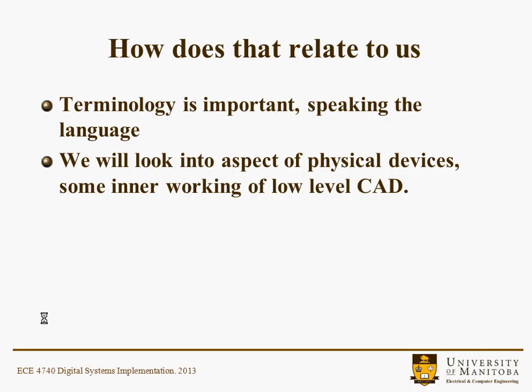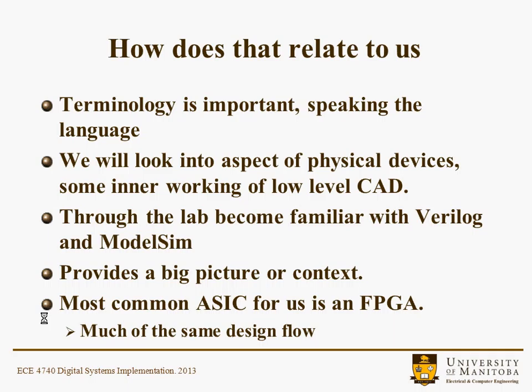Anyway, through the lab, you're going to be very familiar with Verilog and hopefully ModelSim. This little bit that we looked at provides a big picture of context, and for us the most common ASIC is going to be an FPGA, but much of the design flow is the same. There'll be things that aren't there. The scan insertion, for example, won't exist, but you certainly will be aware of them.